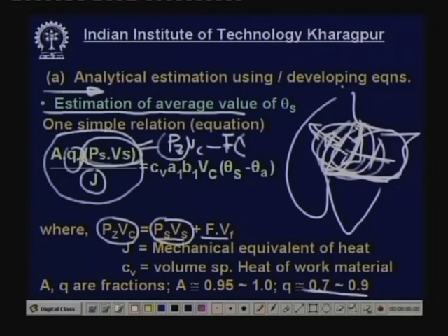deformation alone. Now, in 1 minute, or per unit time, how much heat is contained by the chip if it comes out continuously? That is the cross section of the chip A1 B1, times velocity, so this is the volume flow rate of the chip that flows out, and this is the average temperature at this region, and this is the ambient temperature, and Cv is the volume specific heat. So, flow rate, volume specific heat multiplied by the difference in temperature.